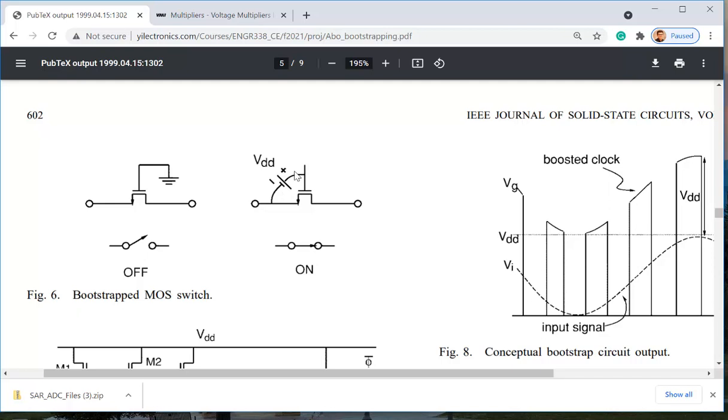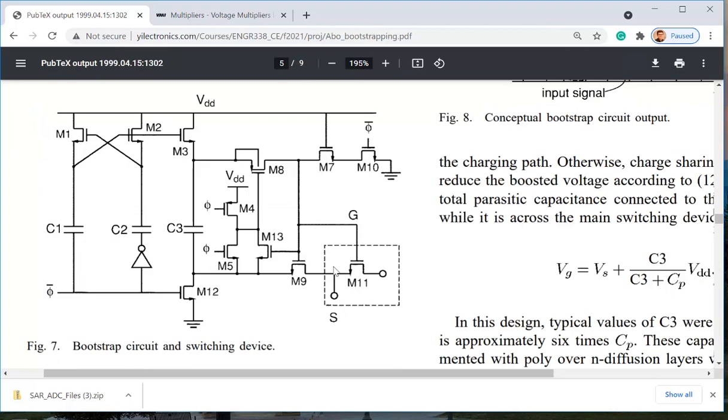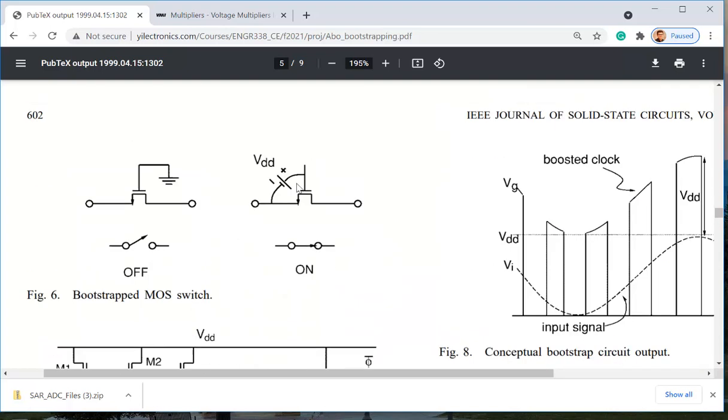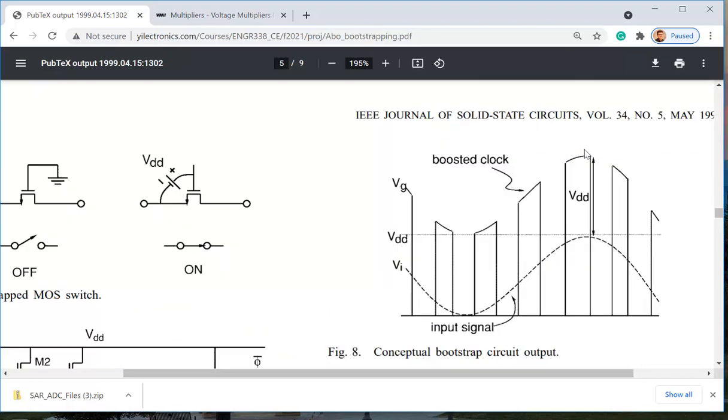You just want to make it happen using all the circuits. So this is just the model, and this is how you implement it. So you are turning on the NMOS using a constant VGS. How? This. And why did it work out? You can look at that: VGS here is constantly VDD, always, no matter what the signal is. That's desired. Okay?